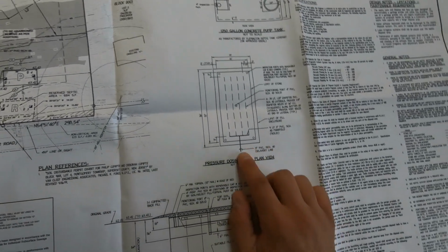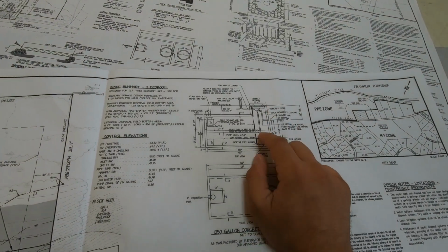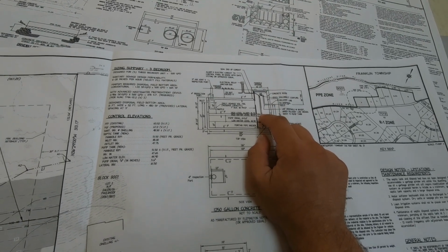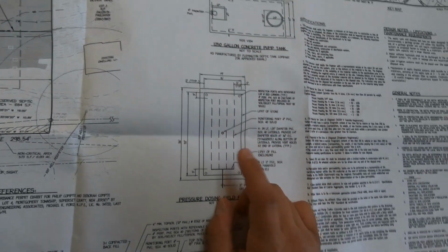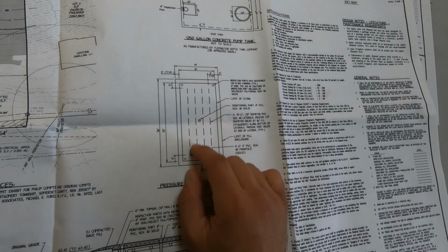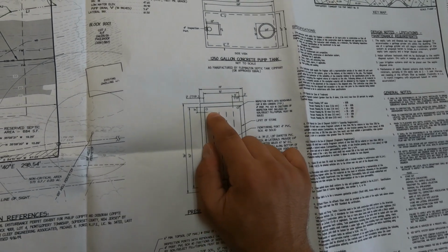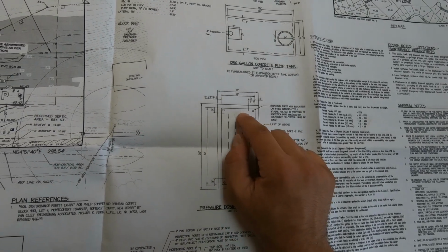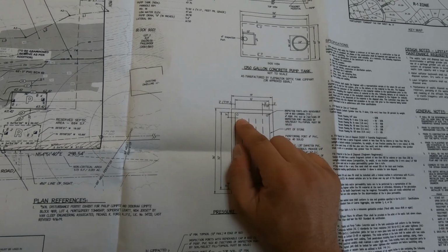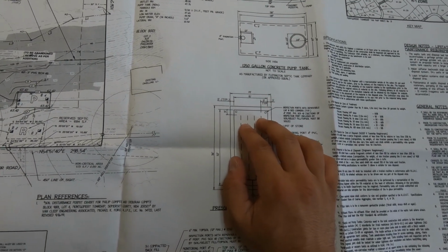But anyway, on a pump system, instead of pouring water in, they actually have to turn on the pump. So they'll turn on the pump. They'll usually lift up the float to activate it, and it'll start pumping water out to the field. You'll know it's working because, one, you'll hear the water rushing through the pipes. You should be able to see the perforations in the pipes expelling water. And at the end of the laterals, there's also a hole drilled into a cap, and there should be water coming out the ends of that lateral cap. All right, so that's how you would check the equalization of flow.